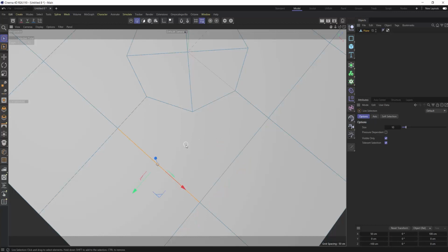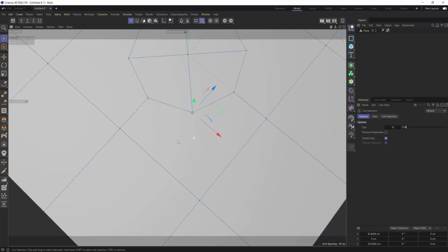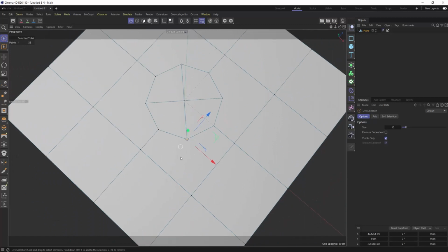This is not a quad or a tri. And a tri is built up of 3 sides and 3 points. So this polygon, and this polygon, all the ones surrounding this are not quads and they're not tris. And so this is improper topology. And they're creating what's called open-ended points. So when we're talking about proper edge flow and that gets disrupted and the point doesn't go anywhere, this is going to bring us some issues. So we'll get into the proper topology here in just a moment and correcting this.